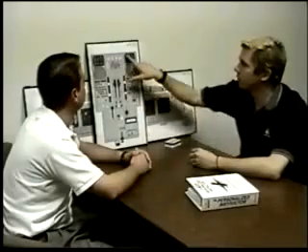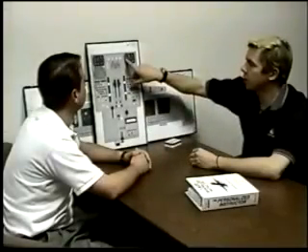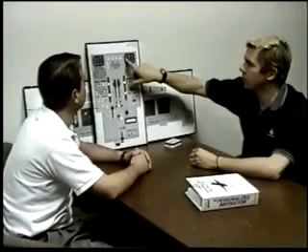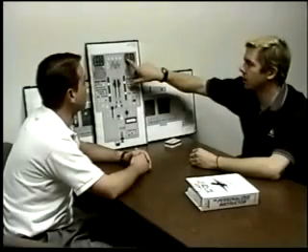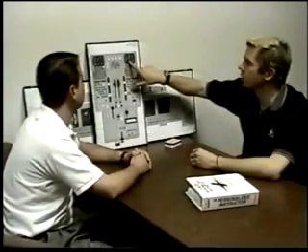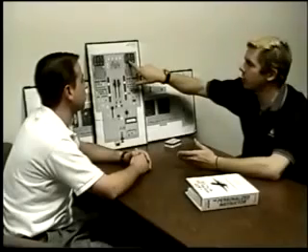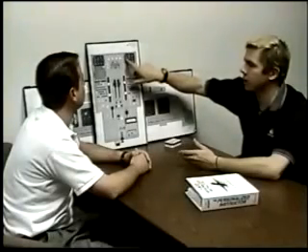To calculate V approach on an A320, we add 5 knots and then a third of the headwind that is entered on this page. Because we're on runway 33 and the mag winds here say 330 degrees at 15, a third of that would be 5 knots. So 128 plus 5 is 133, plus a third of the headwind, which was 5, would give us 138 knots. That would be our V approach.